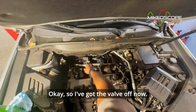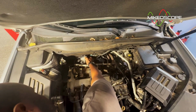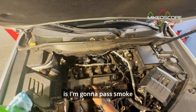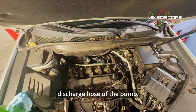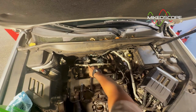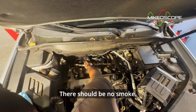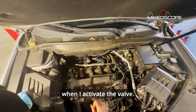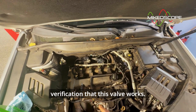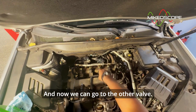Okay, so I've got the valve off now. We're going to go ahead and test the valve directly. So what I'm going to do is pass smoke through the hose, the discharge hose of the pump. And then once I pass the smoke, this valve is currently closed. There should be no smoke. And then I will activate the valve and the smoke should start coming out when I activate the valve. So that'll be the verification that this valve works. So let's do that. And then we can go to the other valve.